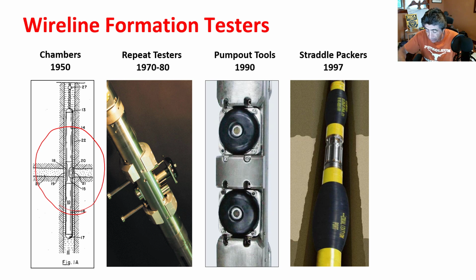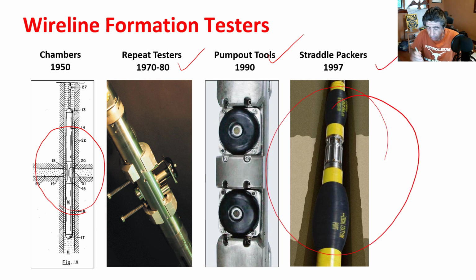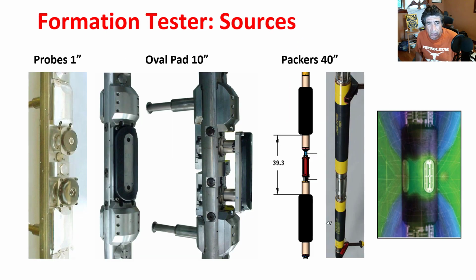So the formation testers were initially based on that same principle of drill stem testing, and we have a number of configurations: repeat testers, pump out tools, or straddle packers. I'm going to be talking about straddle packers in this section because of some very important technical context. But as formation testing technology evolved, we began to have different configurations of formation testers.